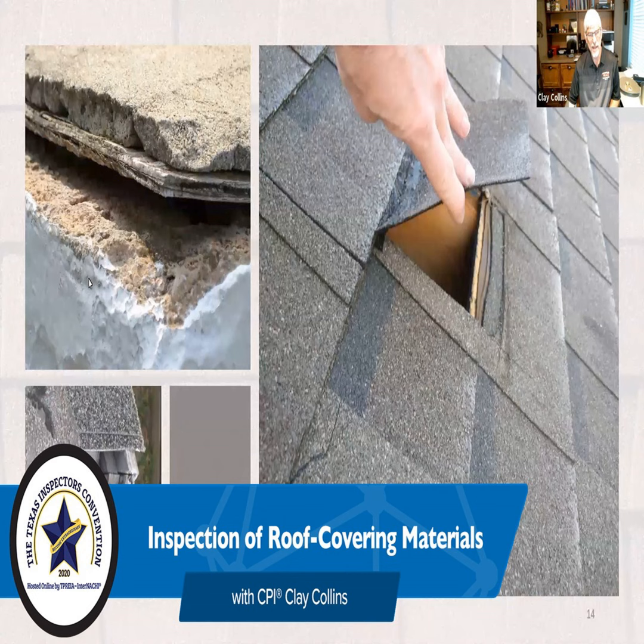And I think that's just because it ran down so well, so quickly, that it didn't have time to saturate that decking there. This one is the chimney cap. It's the mortar cap on a chimney, and that cap was over some plywood. Now I have a problem with the plywood itself being used there, but that's what it was. Couldn't see that from the ground because the best angle you had was up, and it just went right across there, and you weren't able to see the lift or the gap. And then over here, it's pretty clear that somebody cut a hole perhaps for a vent, roof jack of some sort, and then they never bothered going back and putting that in.